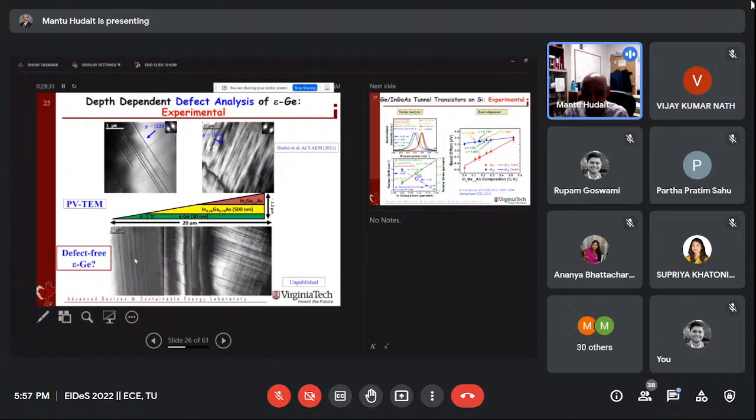No, there's nothing called zero defect. There are some defects that we may not be able to see. What my student said is that the defect count you see is the upper bound, but the actual defects should be less. I asked him, why do you think so? He said, think about a paper. Once the germanium is very thin, that is called plastic relaxation. It's like bending it. Think about a paper, you can flip it. Once you bend it, you can generate some plastic or additional defects when that layer is so thin. So then he came up with these kinds of cool ideas, using all the materials tricks to quantify or qualify the material for the device.